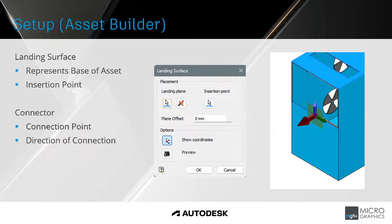Where on the model is that connector going to be? In this case, we can see here on the right-hand side, I've got a connector showing on the cooling line. The large red arrow is the direction of the connector. So that is going to connect in that direction to another object. The blue arrow shows the up direction for the connector. So it's important to pay attention to that. Otherwise, your machine may flip over and connect upside down to something, or the object you connect to it could flip over and be upside down. So you set up your connection point and the direction of the connector that you want to use.